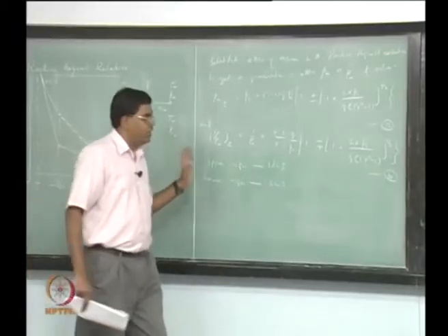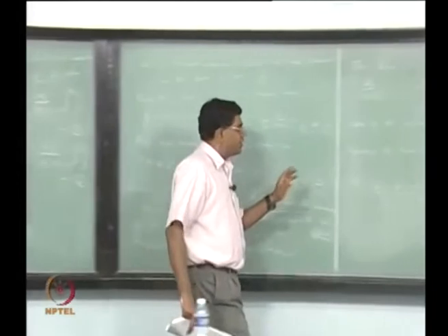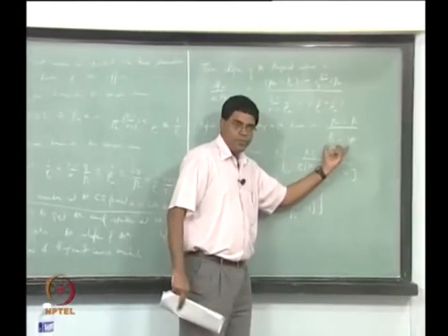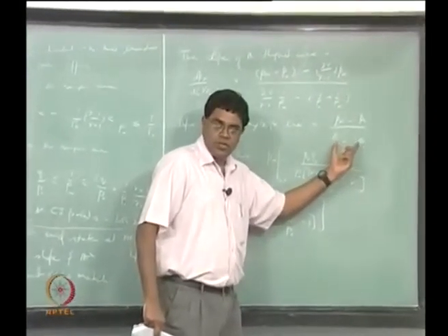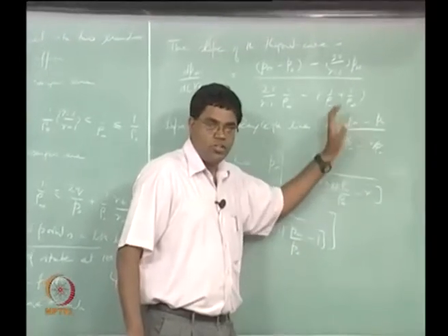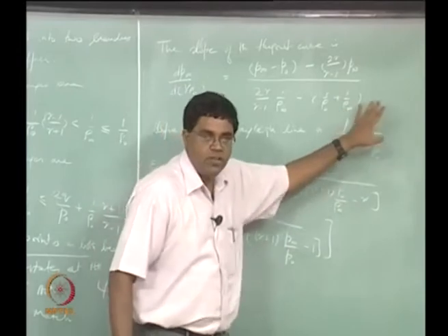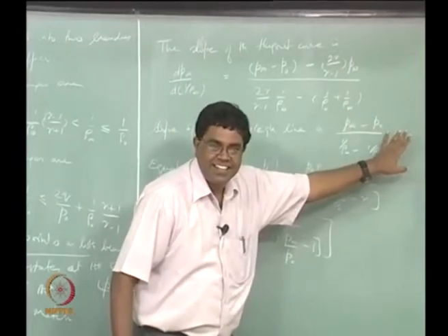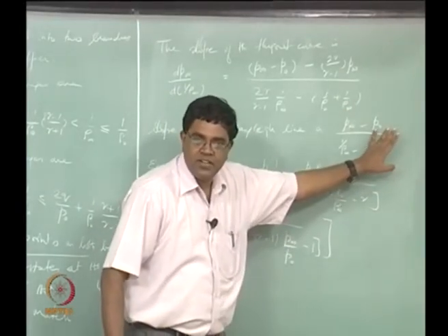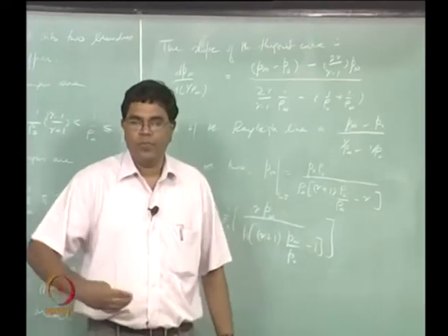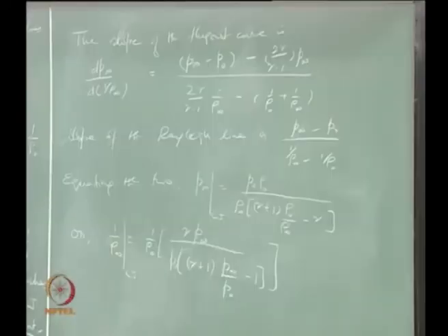So we have really not used the Rayleigh line information except to note that that is the slope, just the slope written in terms of thermodynamic variables. We have not brought in the fact that this is equal to minus m dot squared. So that's what we want to do now. We want to notice that the slope that we had used for the Rayleigh line is actually equal to minus m dot squared, and then get to the flow information.